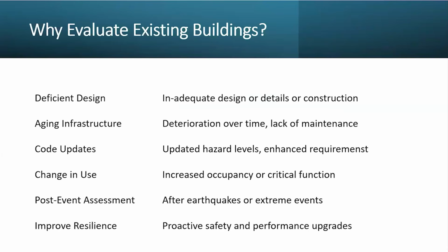The structure may also be becoming old, aging, deteriorating. There's been no maintenance. The codes have changed. The hazard levels have changed. We've seen in many countries that the seismic codes keep being revised, and the way we look at seismic hazard from UBC 97 to the current has completely changed. That means the hazard levels have actually changed because we have more knowledge about hazards.